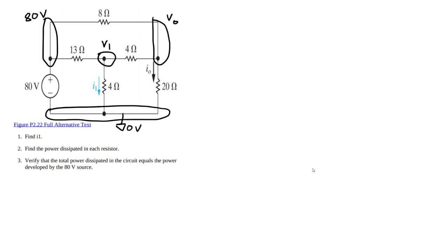So in nodal analysis, we assume that the currents are leaving always. We assume that our node is at the highest potential. It doesn't matter if it isn't, it just means that these currents will be in the opposite direction ultimately. So I'm going to call this I1, I2, I3. These are just so that you know what I'm talking about when I'm writing the equations out.